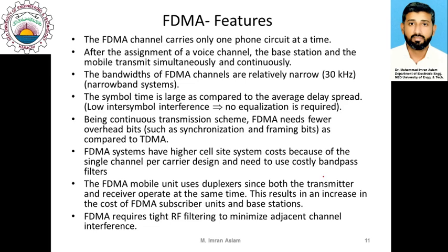So let me quickly summarize important features for FDMA systems. The FDMA channel carries only one phone circuit at a time. So in one channel we can establish only one communication link for that particular time. After assignment of the voice channel, once you have assigned the channel to a specific user, both the base station and the mobile station transmit simultaneously and continuously,